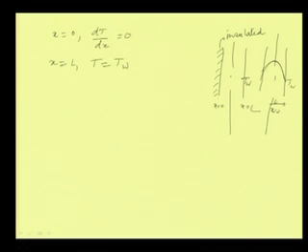So, if we try to draw that, the profile will now be like this. This is the same profile as before, and this total thing represents these total things. So, when one surface is insulated, the profile is shifted like this. This becomes the profile for a plane wall with one surface insulated.